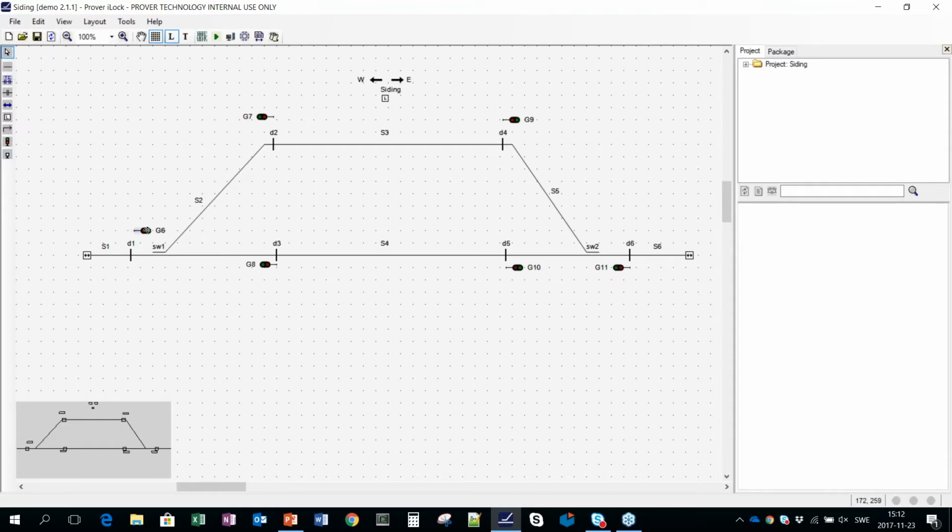I saw that this wasn't put exactly where it belongs. You can see the little red dot here, and it's a bit off the joint, so I move the signal to the joint like this. Now it should be better. And I save this. Okay, I have now added configuration data for the track layout by drawing the track.